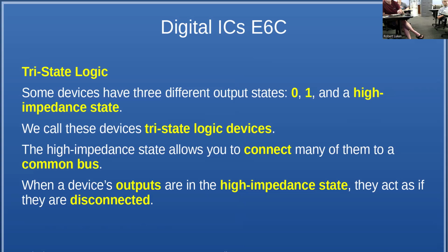They developed what they call tri-state logic so that you could connect multiple devices together to form a data bus. They have an extra control pin that allows you to put them in what they call tri-state mode. It basically disables it, and it looks like a high impedance on its output. So it's effectively switched out of the circuit.